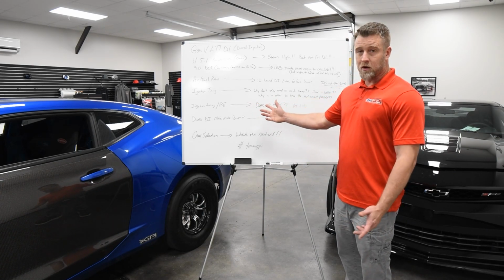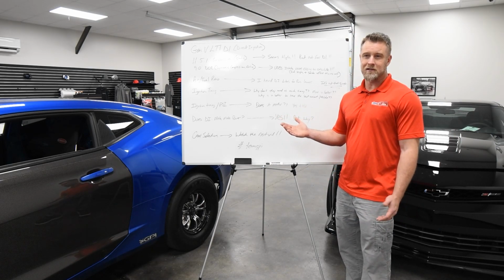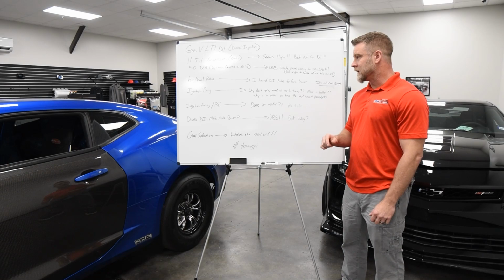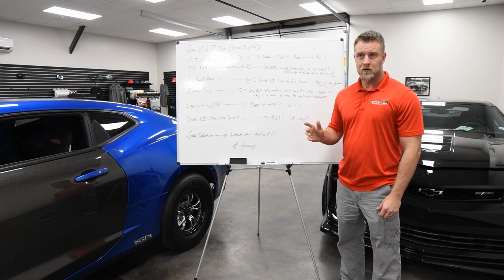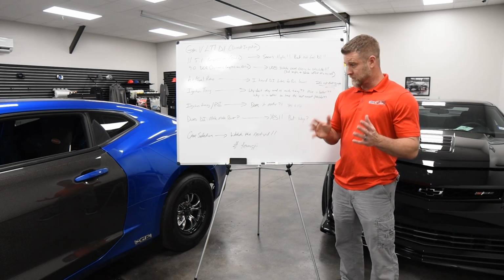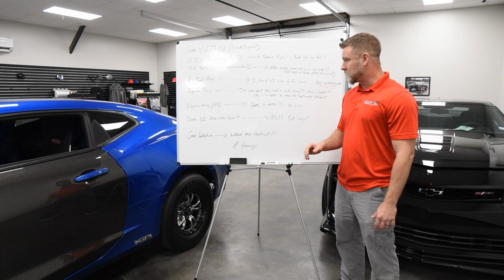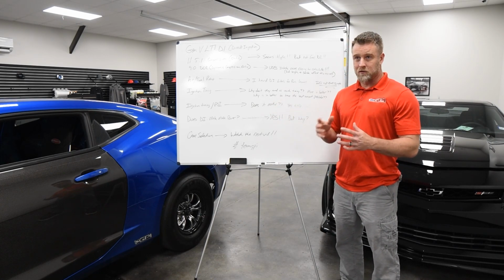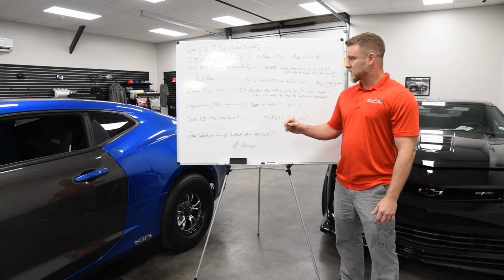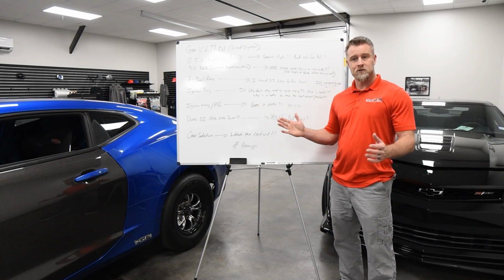Injection timing and fuel pressure. Does it really matter? It does, and it doesn't. Another not simple answer. The injection timing event is very important. The window where you can get the fuel in, you've got about 6 milliseconds of good real estate there, but that's about it. And when you start working the fuel system harder, that fuel pulse gets longer. So to combat that, we will use fuel pressure to turn that up, to shorten that injection event.